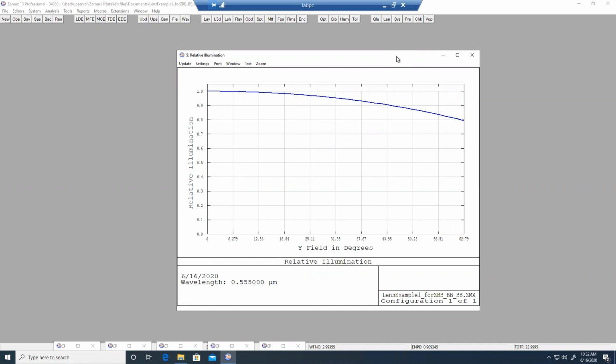But why this is important is because the human eye and software can both recognize light falloff. Depending on the exact application, the relative illumination percentage, the exact drop-off from center to edge, may be more critical to evaluate. The other chart showed the spatial frequency, and you explained that the spatial frequency you would pick is somehow tied to the pixel size of the sensor. Why is that not listed here?